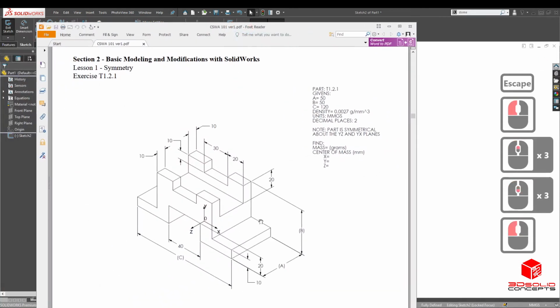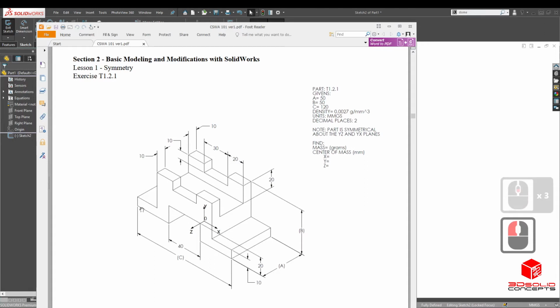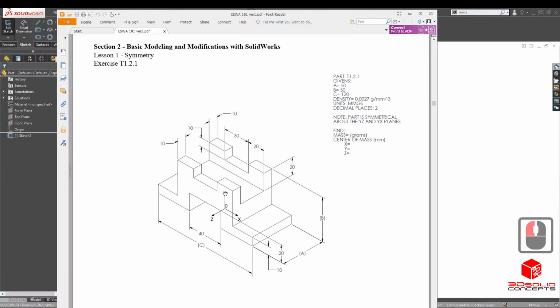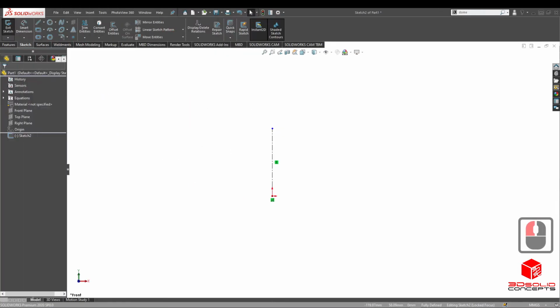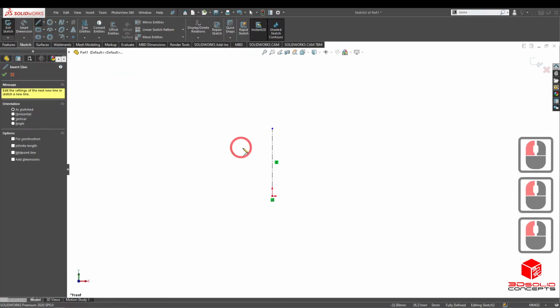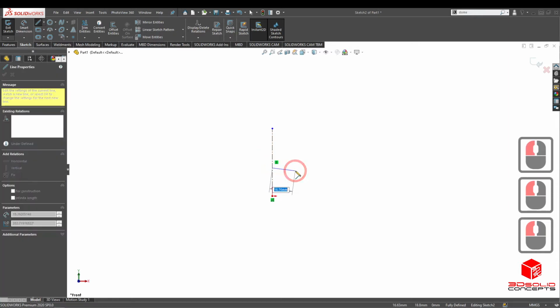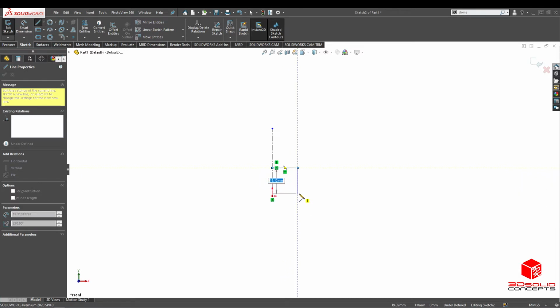So I'm going to rough out this shape that you see here. This leg, and then a bridge, and then another leg. Actually, it's just going to be one side, and I'll show you guys how to make this symmetrical. So I'm going to click the sketch right there. Now down here, you want to make sure that you grab that constraint there. So right here, you hover over it, and then you make sure that you have the vertical bar and the horizontal bar.